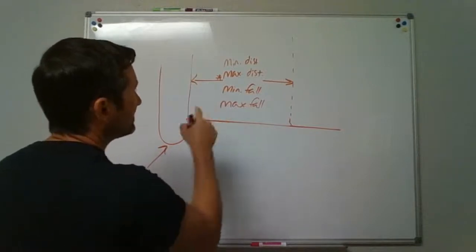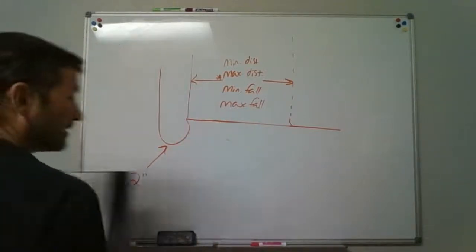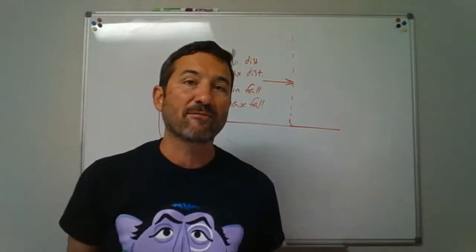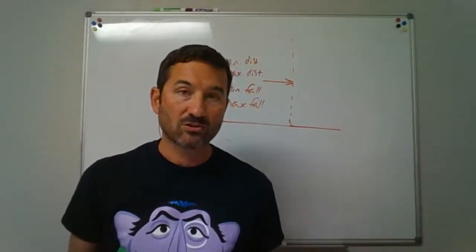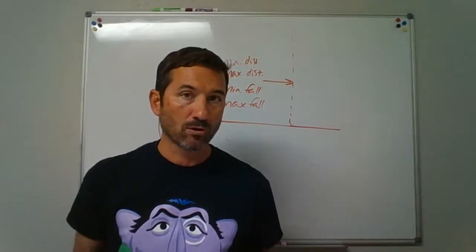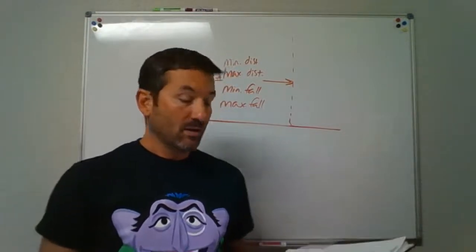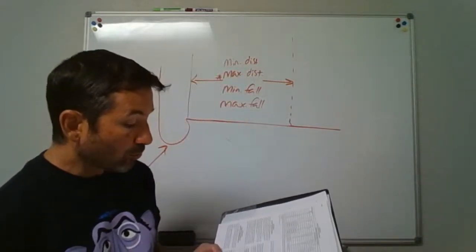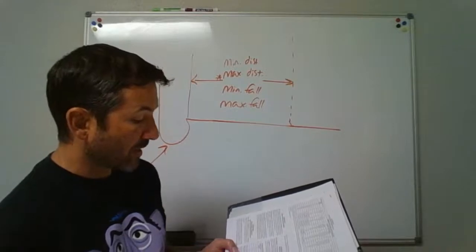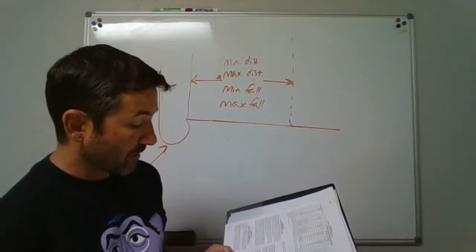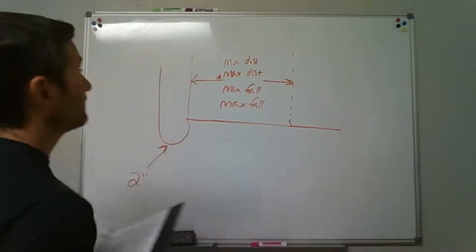Now, if you look at this chart, you take the size of the trap, multiply it by 4, and that's going to give you the answers for all of those. Now, then there's another, venting the fixture drains. The total fall in the fixture drain due to the pipe slope shall not exceed the diameter of the drain of the fixture drain.